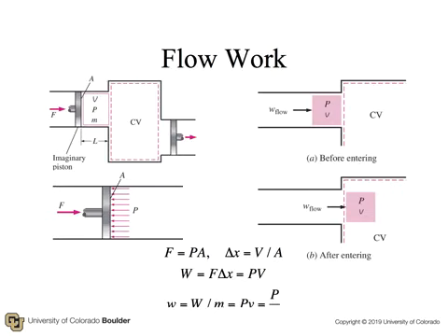Flow work is illustrated in this slide, taken from Cengel and Boles' fine undergraduate text. To push mass into an open system requires work. The force is equal to the pressure difference across the volume times the cross-sectional flow area. The distance is equal to the volume of material entering divided by the flow area. The work is then equal to the pressure times the volume.